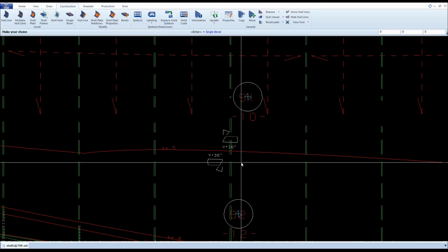Bevels are presented only when they belong to a solid block or when the environment show-bevel has been set to yes. Presentation depends on the setting presentation, bevel settings, presentation type. So if you have set the setting to text or model and text, the text will be presented. And if you have set to model or model and text, you will see the model.